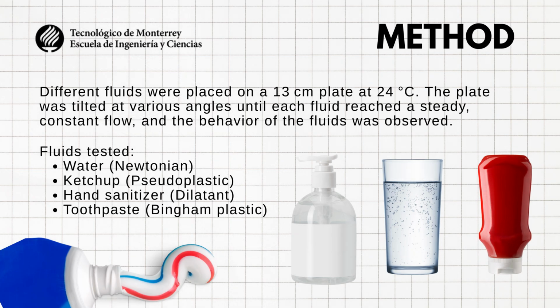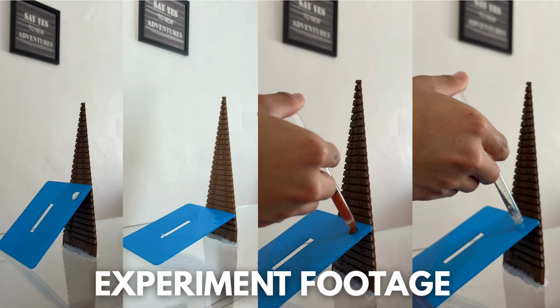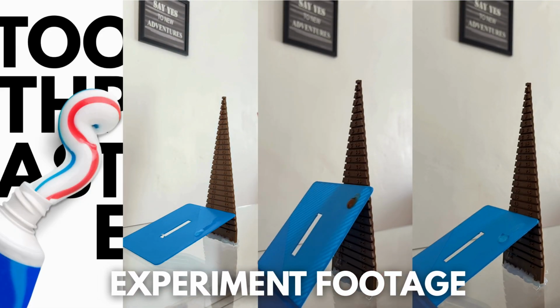Different fluids were placed on a 30 centimeter plate at a temperature of 24 degrees Celsius. The plate was tilted at various angles until each fluid reached a steady, constant flow, and the behavior of the fluids was observed. The fluids tested were water as a Newtonian fluid, ketchup as pseudoplastic, hand sanitizer as dilatant, and toothpaste as Bingham plastic.